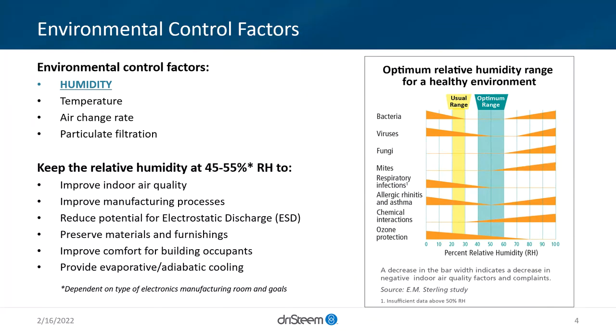But once we get in that control range, and once that's been established for a facility, these types of facilities usually have tight control. What I mean by that is plus or minus 2% RH. Roughly, to maintain that would be about a 0.9 degree F dew point control. So really, once you've established what you need, tight control is obviously important for consistent stability.